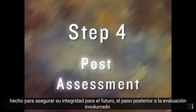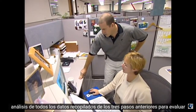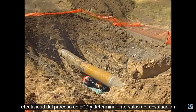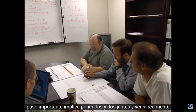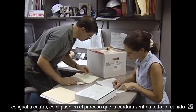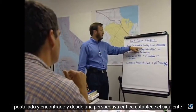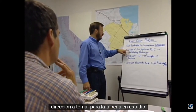The post-assessment step involves analyses of all the data collected from the previous 3 steps to assess the effectiveness of the ECDA process and determine reassessment intervals. This important step involves putting 2 and 2 together and seeing if it truly equals 4. It's the step in the process that sanity checks everything gathered, postulated, and found, and from a critical perspective, establishes the next direction to be taken for the pipeline under study.